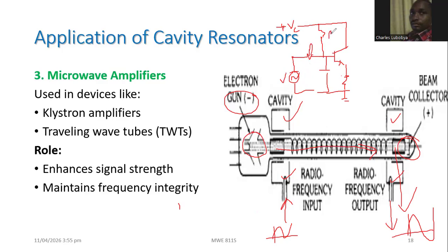The resistor there, capacitor there, right? Here you can actually put in an inductor. Okay, so you have the inductor and resistor. And then what will happen is that because you've pushed in that signal, once the base current flows there from the VCC, this signal gets amplified.